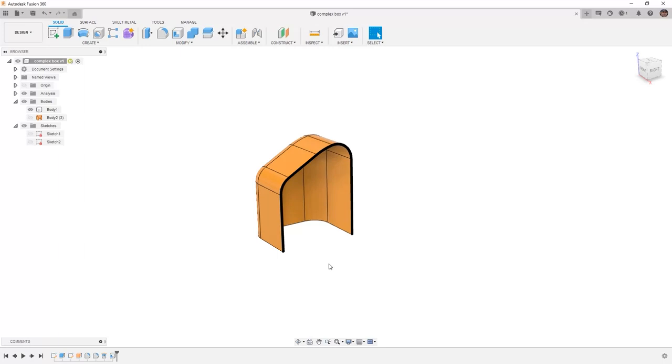So while some things will be able to be updated based on Replace Face, like fillets on the vertical and the horizontal edges, there are certain features that are still going to be timeline dependent. Things like shell, because it's not going to recalculate the shell based on the new position of that top face, but it will carry those fillets up with it.